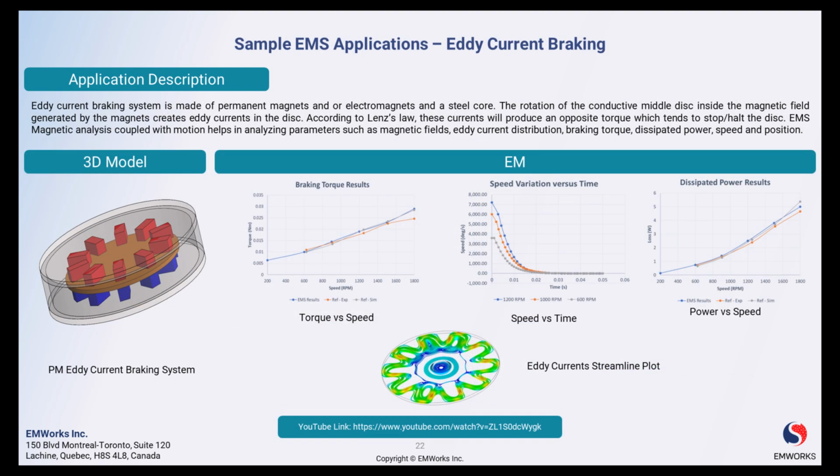Next, this EMS 3D application model demonstrates the simulation and analysis of an eddy current braking system containing permanent magnets and a rotating steel core. Key results obtained include braking torque versus speed and power dissipation versus speed curves. The magnetic flux density streamline plot also provides insights into the electromagnetic field distributions and eddy current effects in the brake core.